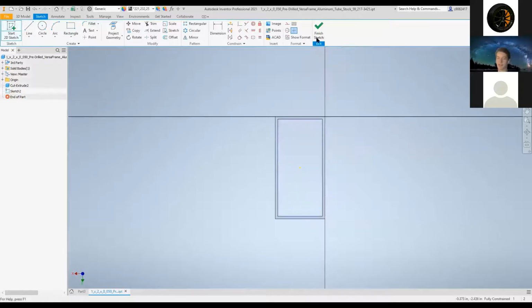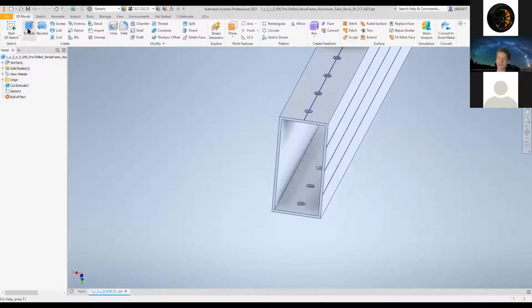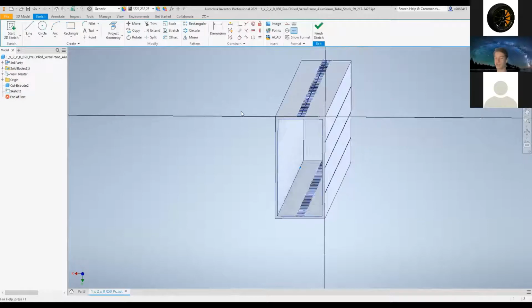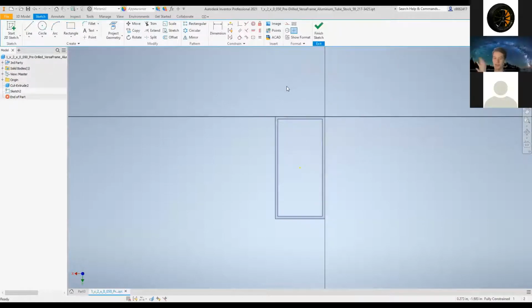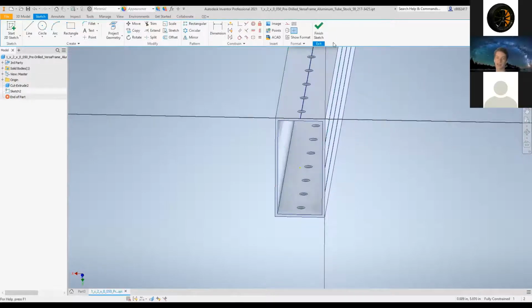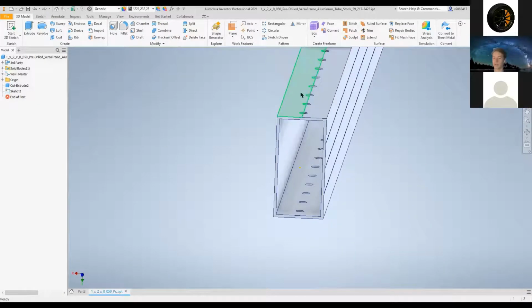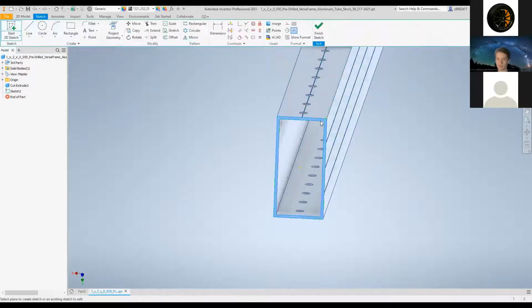Yeah, I probably went kind of fast, but what I did is I started a new sketch on the face, and you have to actually bring a sketch of the VersaFrame tubing from the side so that when you're cutting it, it's actually cutting the tubing. So essentially you're making a sketch to modify the VersaFrame tubing as if it was a regular part, and you're just cutting into it. Yeah. So make a sketch. And make it on the front face.